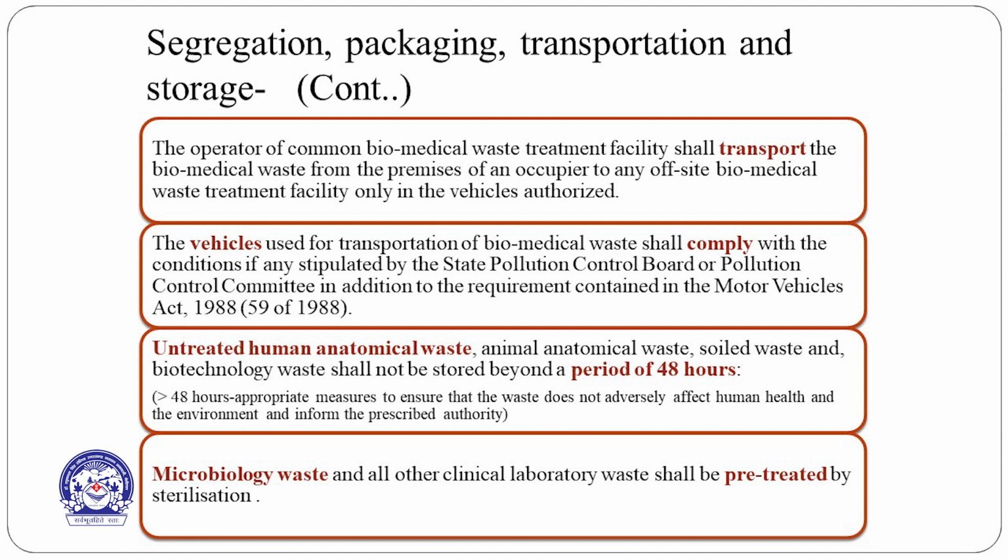In case due to any reasons the waste has to be stored for more than 48 hours, then appropriate measures should be taken to ensure that the waste does not adversely affect human health and the environment, and the prescribed authority should be informed as early as possible. Microbiology waste and all other clinical laboratory waste shall be pre-treated by sterilization.